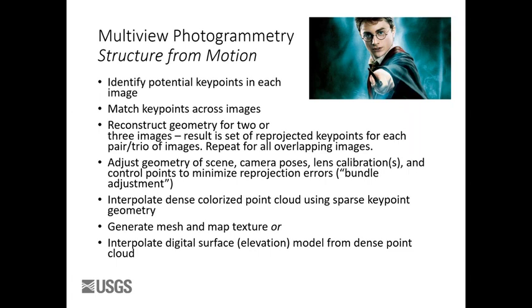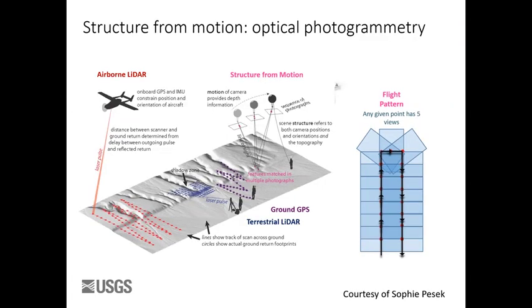And so most structure from motion people solve the camera calibration using the data that they got from all these images. Then after you do that, and you've got the tie points and you've got the geometry all straightened out, then you have to somehow add the whole color from the images. You've only taken a subsampling of a few points, maybe 1,000 points per image out of a 16 megapixel image. Then you have to add all those other 16 megapixels back in and put some kind of color onto the geometry. So there's kind of an interpolation problem of filling in the gaps. And then you can finally generate either a 2D product or a 3D product, and put that signal on there.